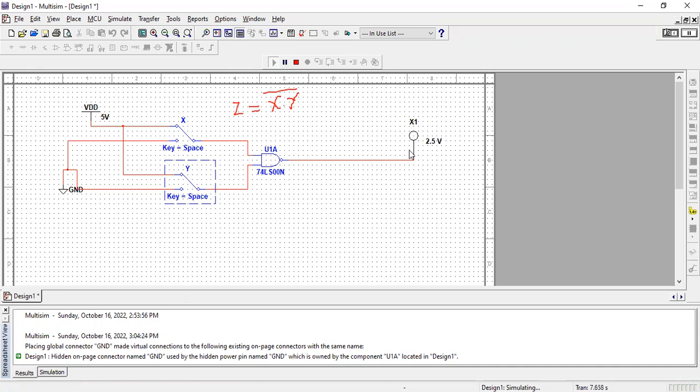In short, we can say that if we invert the output of our AND gate, that gate will be basically NAND. This bubble basically represents the circuit diagram of NAND gate. Similarly, you can also design NOR gate, that will be the invert of the OR gate. So next I'm going to design additional circuits like exclusive OR and exclusive NOR.